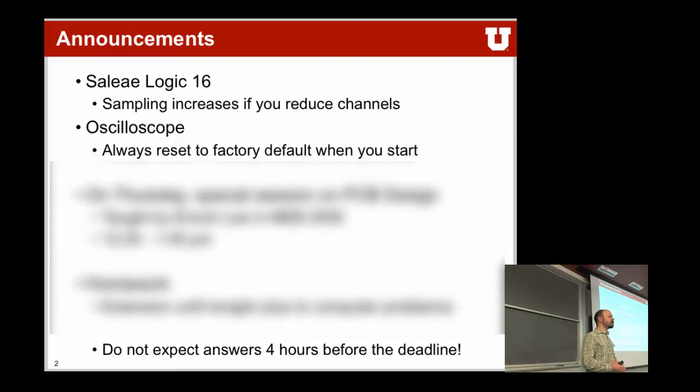Try not to use the auto function. Oftentimes it doesn't really give you what you want. If you know what type of signal you're looking at, try to use the dials to go to the range where you think your signal should be and see what's actually there. Oftentimes you will find it much faster that way. Sometimes the auto function will just zoom into some of the noise on your lines and you just don't understand what's really going on.